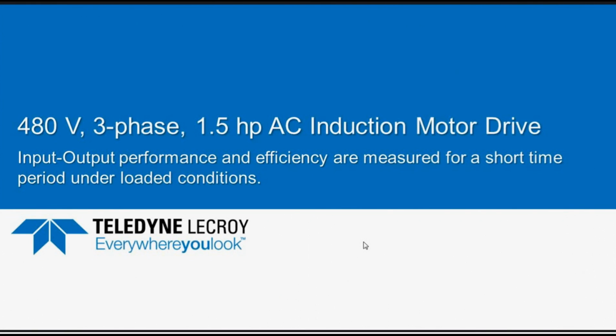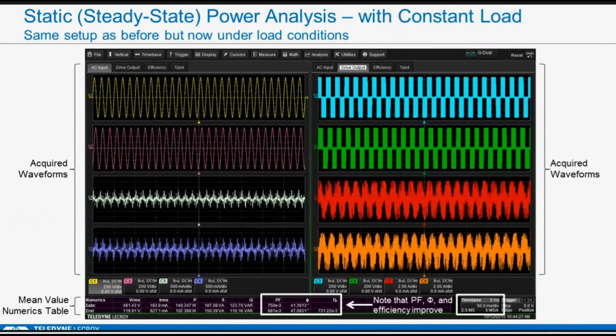Okay, so that's a static test. Now, that's very similar to what you might use a power analyzer for. This is now the same test we did before, but this time we're running it under a load condition. So what you're going to see is the current increased here on my drive output, and I've changed the scaling. Otherwise, I've used the same time period.